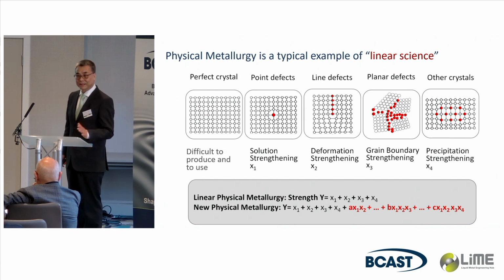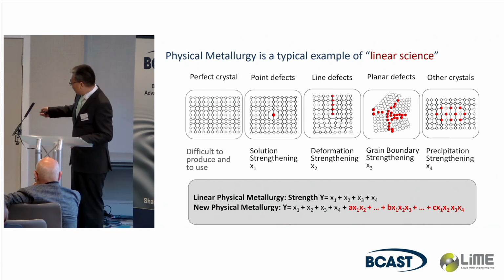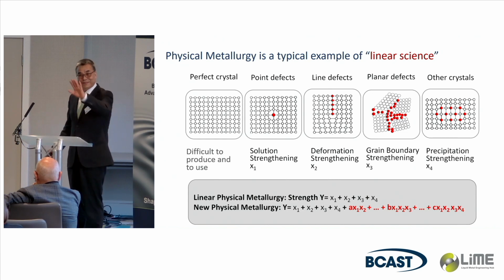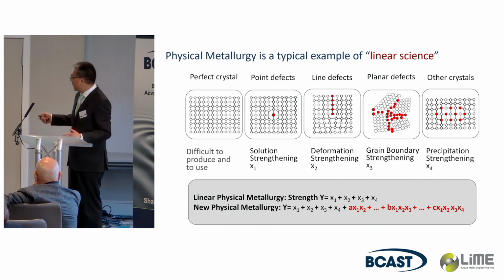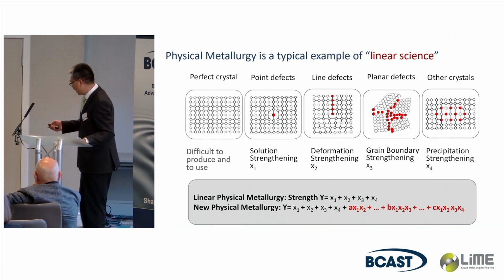That's what you get. And recently, working with Constellium, and the Constellium boss is sitting right behind there, we'll be working on interaction between different factors. We'll be able to push the yield strength on industrial scale over 400 megapascals, and 425 routinely, and even more. And I'll come back to this later.